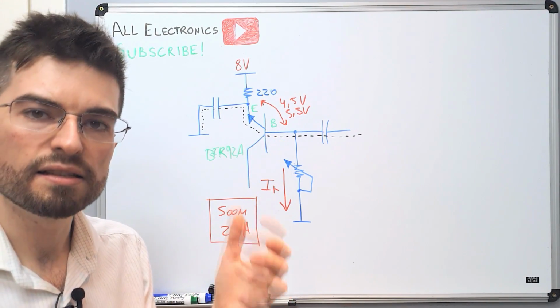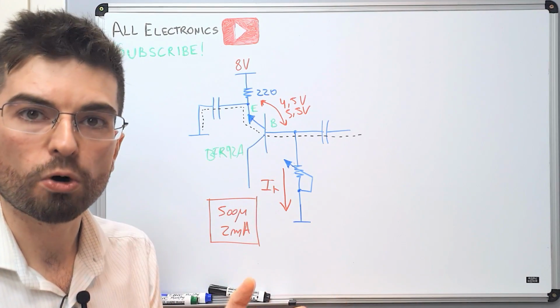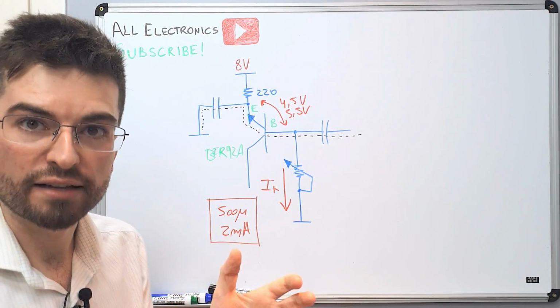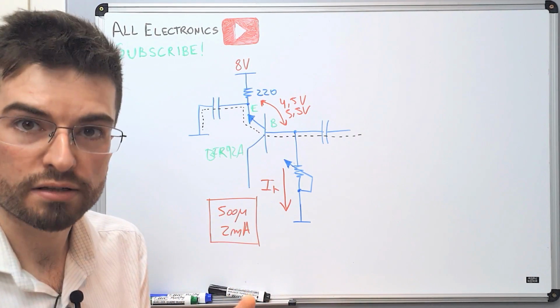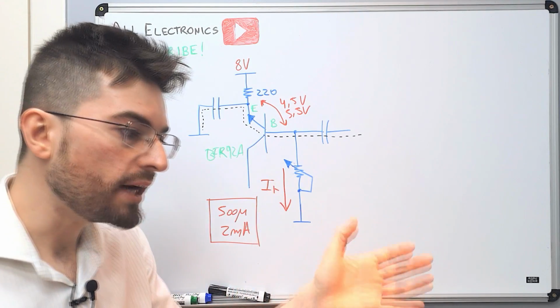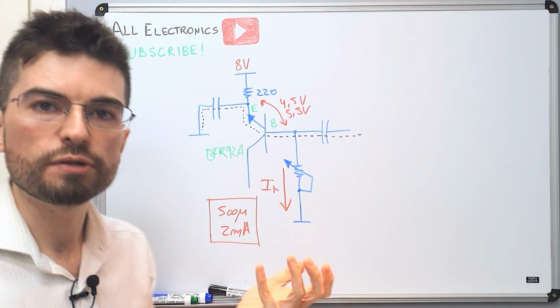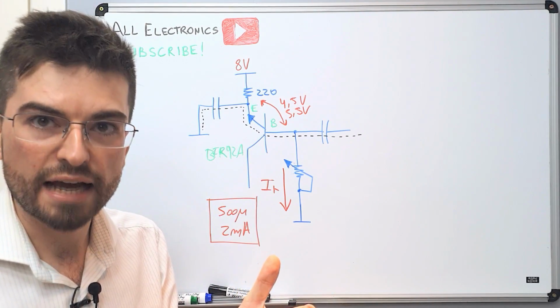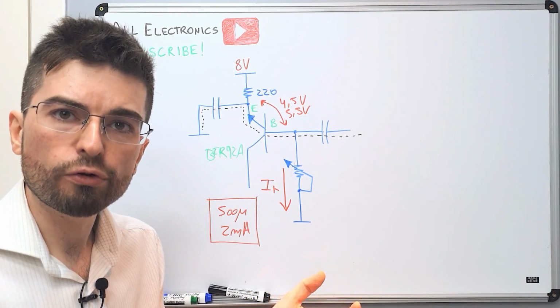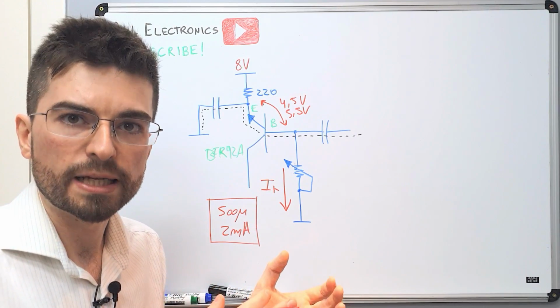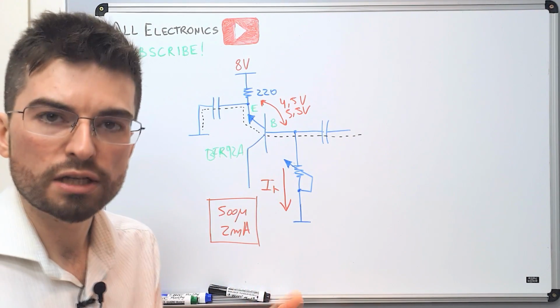In this case, the PN junction is working more in the avalanche breakdown mode, by the avalanche effect, that actually generates more noise. In practice, we don't have one effect or the other effect. We have a combination of both. For this transistor here, we are more on the side of the Zener effect, but of course in practice a little of avalanche breakdown is also happening in this case, contributing to the generation of noise.